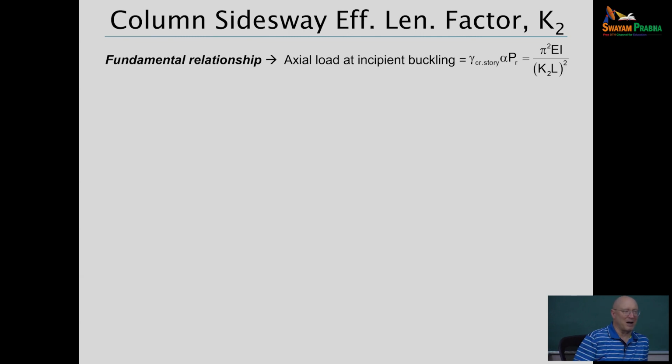But you still may want to calculate a K factor because it helps you understand what's going on. That's where I always tell my students at Georgia Tech, the effective length method is a misnomer. It's the buckling analysis-based method. It's not the effective length method.